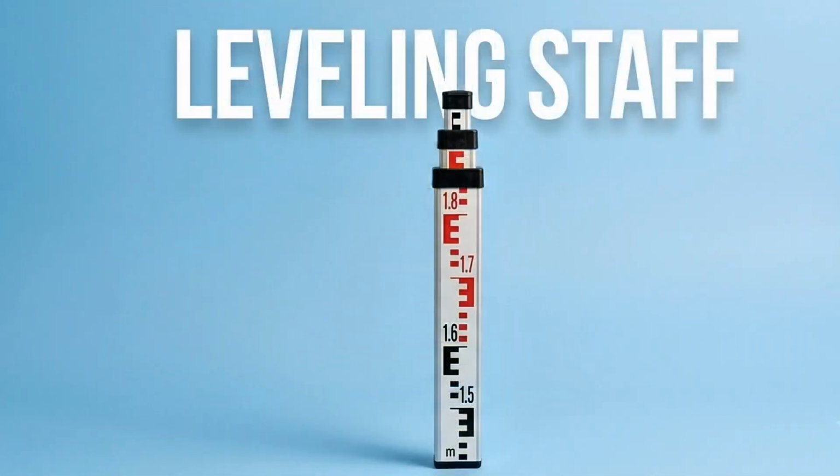A leveling staff is used together with a dumpy level or automatic level to determine differences in elevation. The staff has clearly marked graduations that can be read through the telescope of the level. By comparing readings taken at different locations, surveyors can calculate changes in height and establish accurate construction levels.